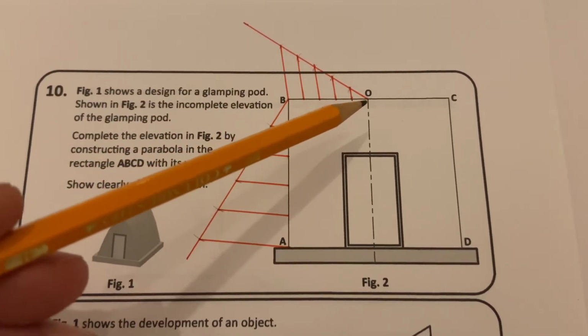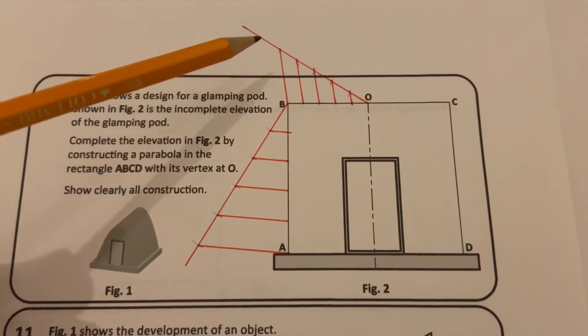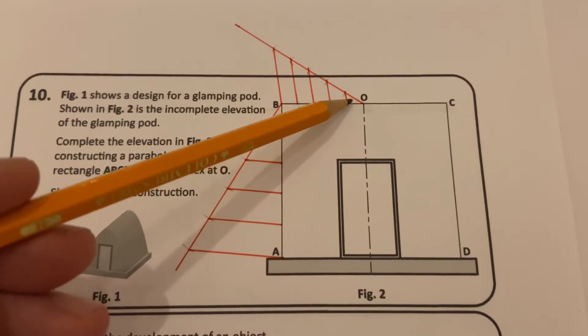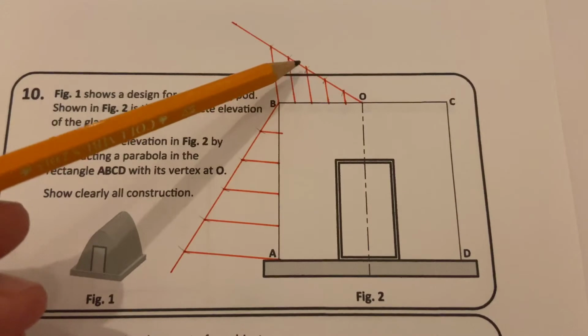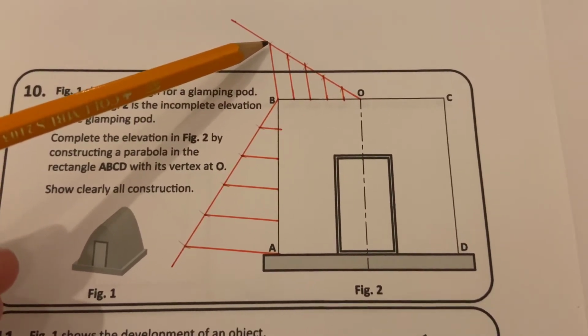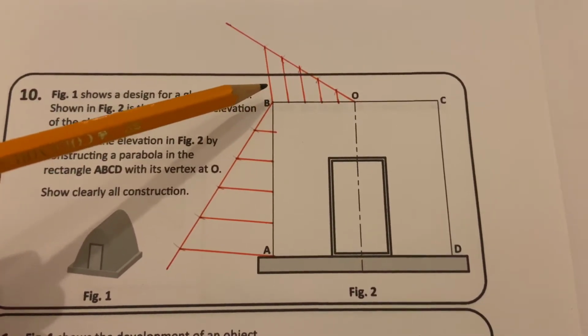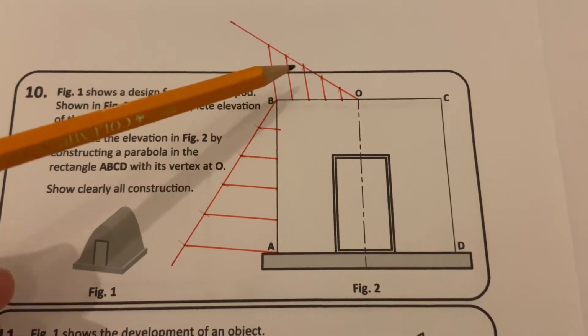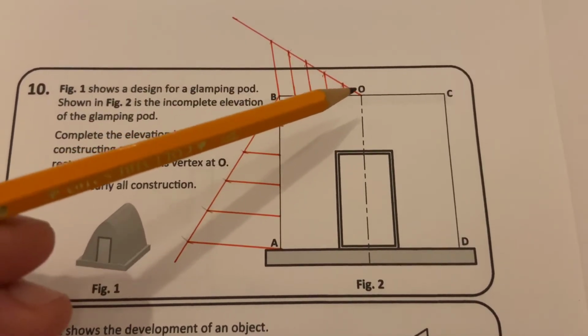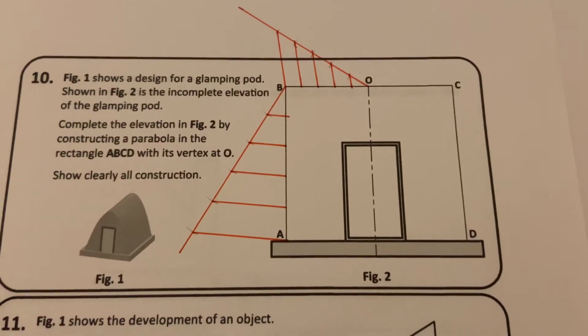In a similar way we draw a line at any angle away from O. Again, using our compass, mark 5 equal divisions along that line. The last one we join back to this, and then using sliding set squares, bring these lines back parallel, dividing this top line into 5 equal parts.